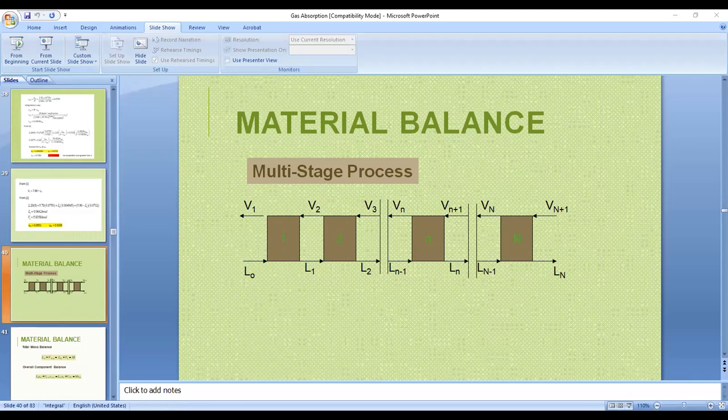And just like what was discussed to you as well, when you're using the inert streams here, L prime and V prime, you're going to multiply them with the mole ratios, not mole fractions. So these are mole ratios when we are talking of a two-component system.